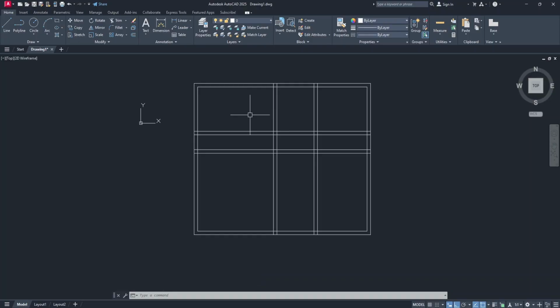For the other part of the house, now we have to trim some, so select the trim up here on the modify panel, select trim. If it shows you something like this, simply click on enter. Else, if you click on it and it shows you directly to start trimming, just trim away. So select trim and trim these two lines and then press enter.